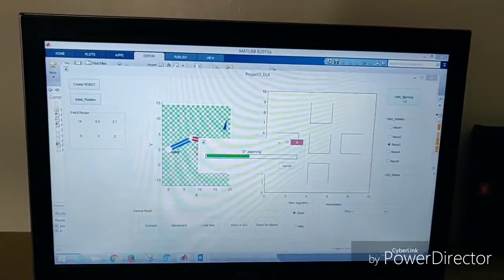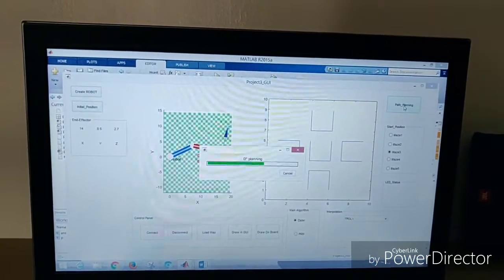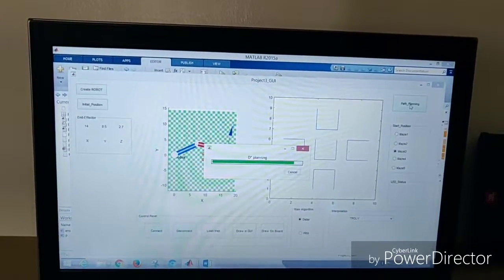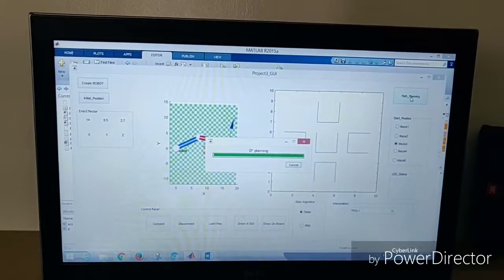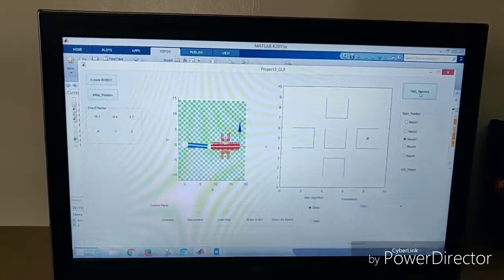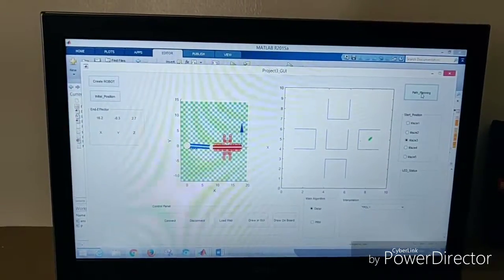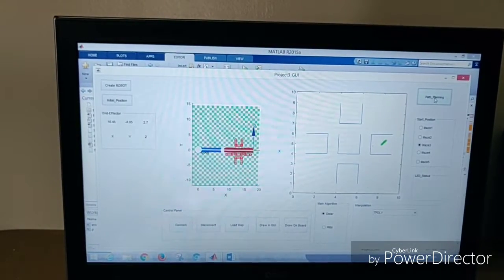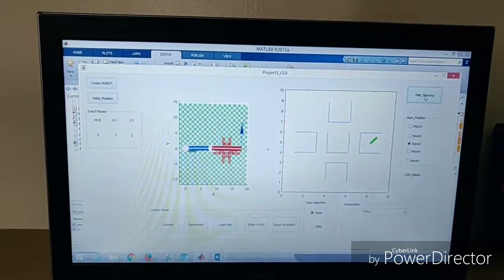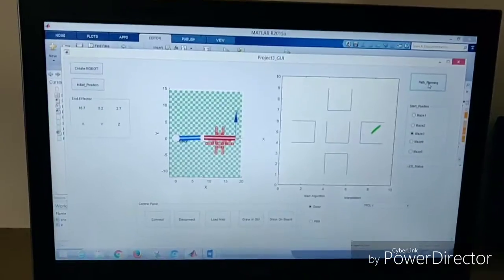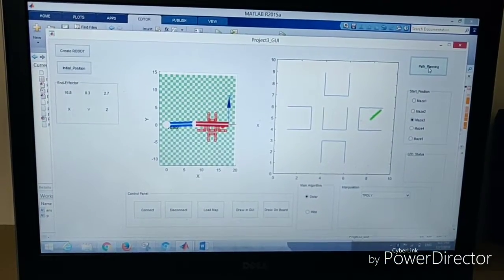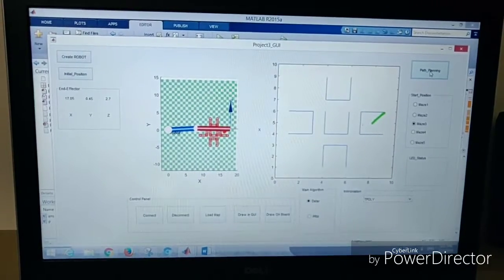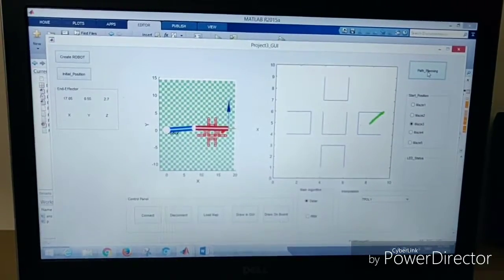Right now we are giving only 3 points between each pair of nodes that D-star connects, so T-poly considers 3 steps from one node to the next. It may take a lot more time than the method without interpolation, but this path is smoother and will not have any distractions while drawing from the start position to the goal position.